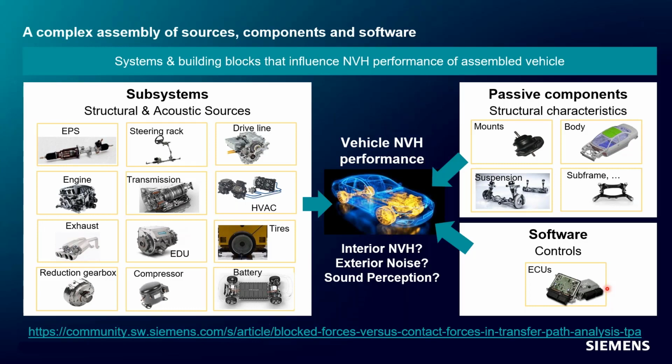This virtual prototype assembly gives you a way to look at all the information, take these different factors into consideration, perform NVH analysis, and then produce meaningful results that can be viewed in an easy and intuitive way. Now, the information needed for this type of analysis from the active components can come from physical testing or from simulation, like Simcenter 3D simulation, for example. Similarly, for the passive components, there are certain FRFs between the input and the output for each of them. We need those FRFs, and they again come from test and CAE.